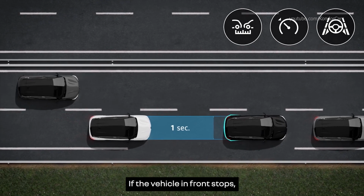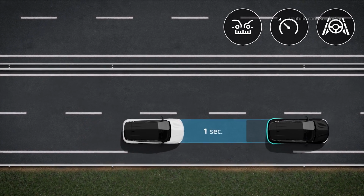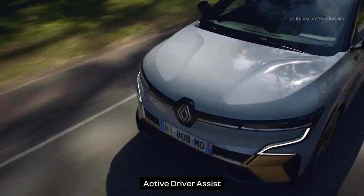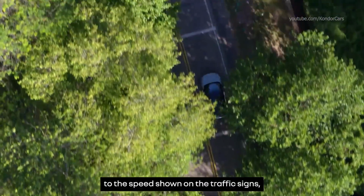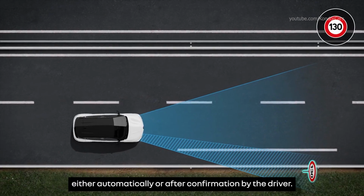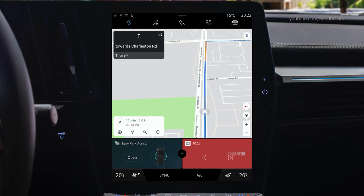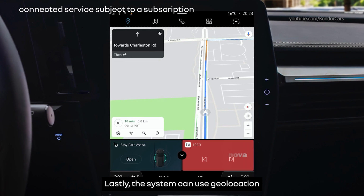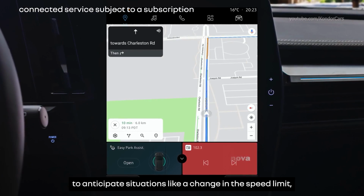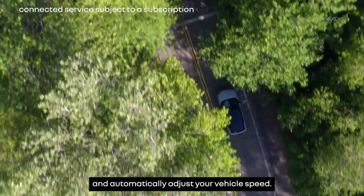If the vehicle in front stops, the system can brake your vehicle to a complete stop and move off afterwards. Active Driver Assist can also adjust the vehicle's speed to the speed shown on the traffic signs, either automatically or after confirmation by the driver. Lastly, the system can use geolocation and connected map data to anticipate situations like a change in the speed limit or an upcoming bend or roundabout and automatically adjust your vehicle's speed.